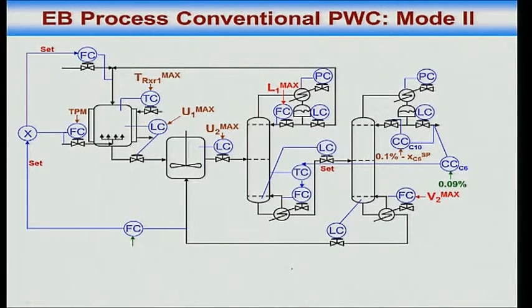But please note, when you think about it, what is actually happening is, I am just transforming what is happening here to here. This loop is transforming here to here. Total benzene is increasing. To increase total benzene, you will actually get the boil up to increase. Yes or no? So the problem remains.